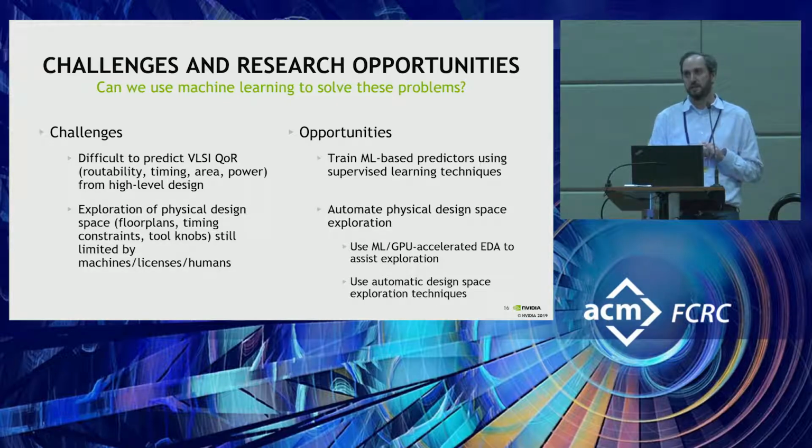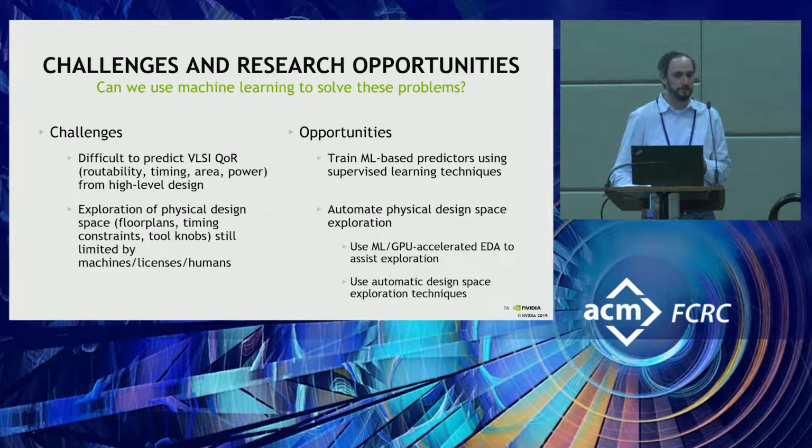The reason is that the timing models are slightly different between the C++ and the RTL. So you could have a bug in your source code that just wasn't exposed because it was impossible or hard to generate the case that would have led to the bug being exposed after the HLS tool does hardware pipelining or hardware scheduling. So I think those are still open questions that need to be solved, and I know some people are working on them. That's probably the way I would answer. I think on QoR, people are starting to be pretty much convinced. That was an argument like 5 years ago, that the QoR is worse. I think people have now shown that the QoR is pretty good.